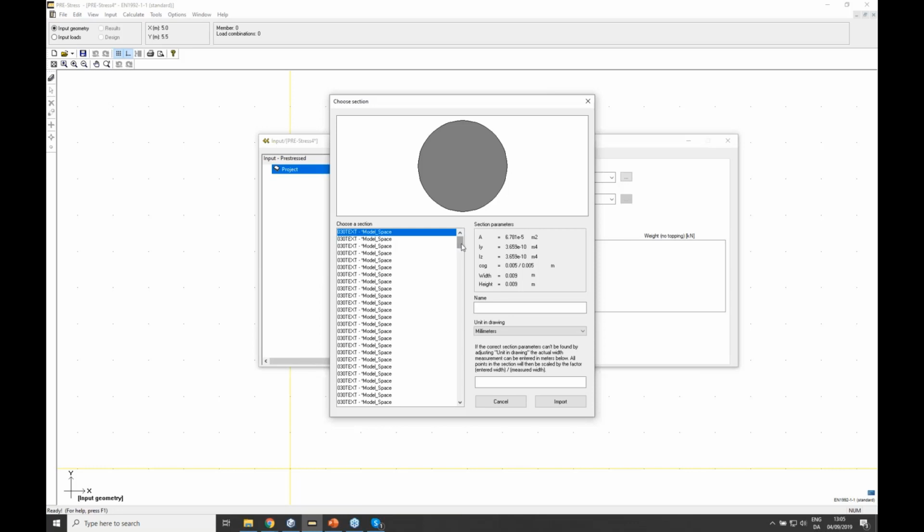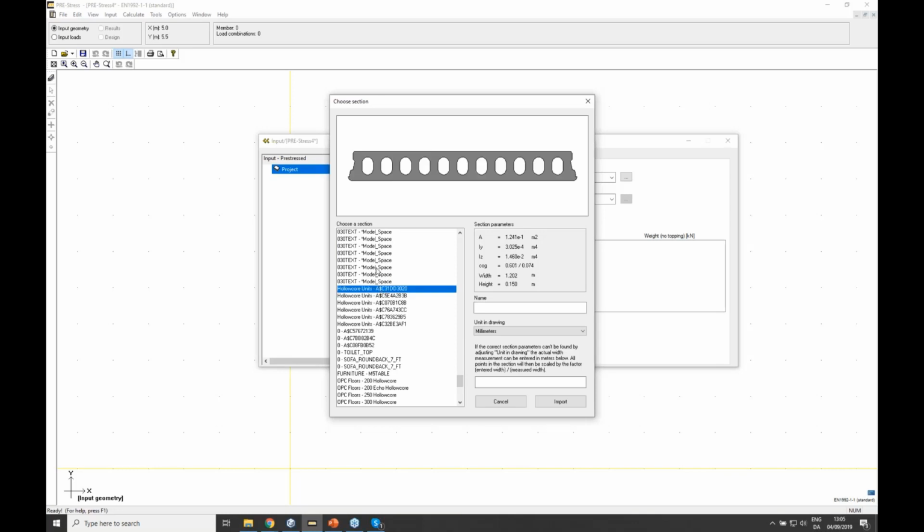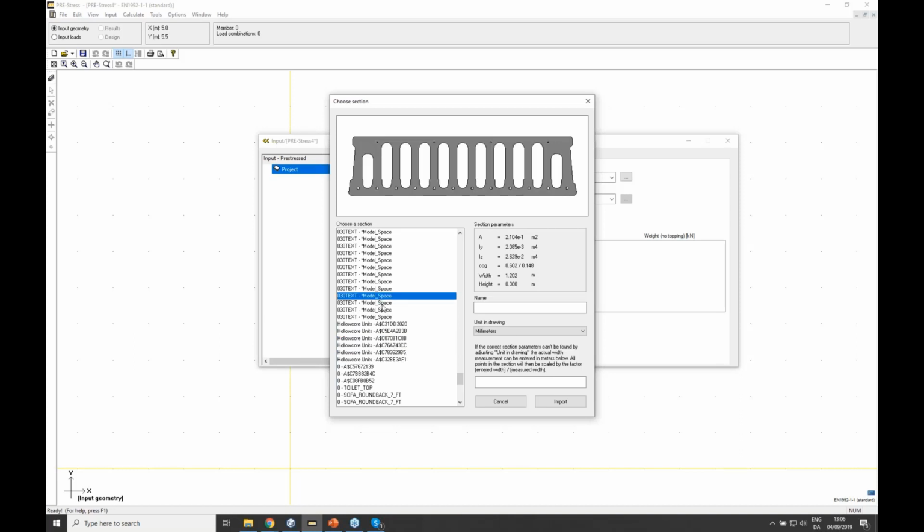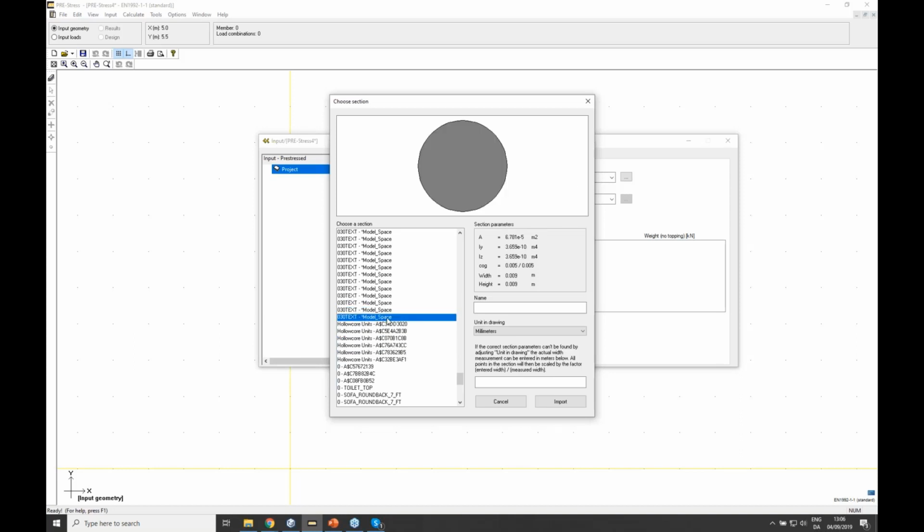interested in. Of course, my recommendation is to have a clean file in AutoCAD. And by clean, I mean just have the contour of your cross section and the holes. Those are very important because that's what PreStress is looking for. As you could see, my drawing was a little bit messy. I had all sorts of marks on it, of symbols, but I use that so I can show that you can also have it like that. PreStress will identify the profiles that are there, and it will also identify other small shapes, which in this case are useless.